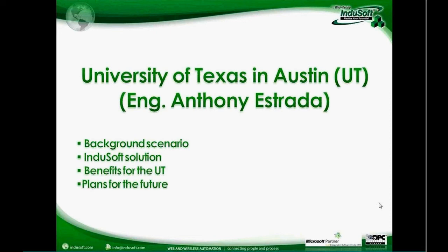And the camera manufacturer provides an ActiveX control or .NET control that can be easily integrated to InduSoft Web Studio to display live images from the cameras. And depending on the features provided by the camera manufacturer, you can even control the camera, pan, tilt, or zoom the camera from InduSoft Web Studio. So the answer is yes. You can display live images from InduSoft.